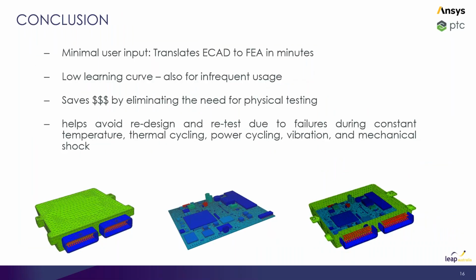So the conclusion is, we really like that workflow because it requires minimal user input. So it's very quick to translate your PCB into a good finite element model. And then, of course, the post-processing gives you a good measure to understand really how long my board will survive later on with all those different physics involved.